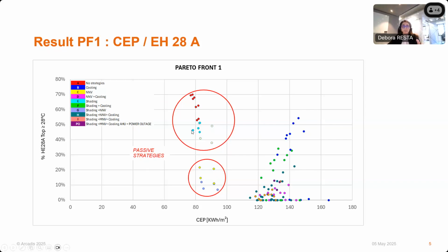In particular, the results underscore how the solar factor alone can impact overheating, with external solar protection alone reducing overheating by 20%. Overheating values below 30% for passive solutions are represented by natural ventilation, where the possibility of opening all windows and creating cross ventilation is feasible. This option is not always achievable and depends on the geometry.